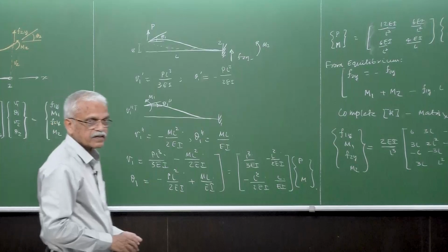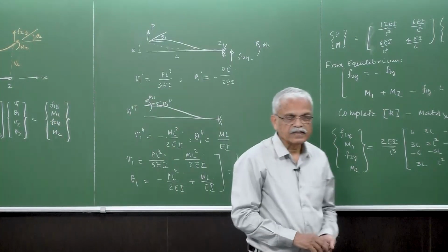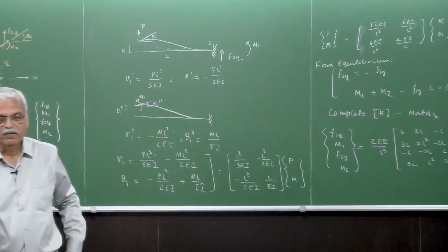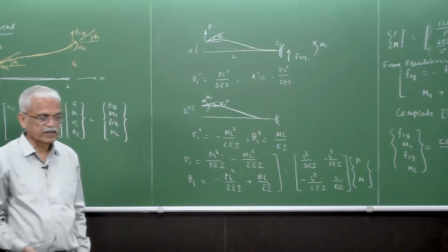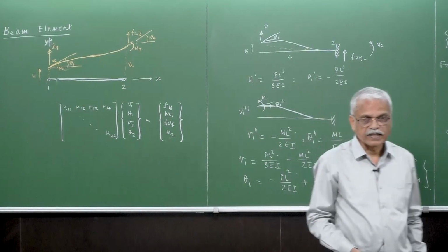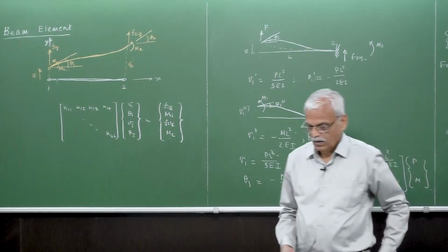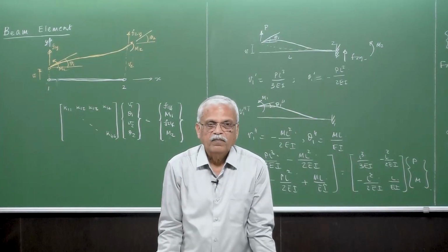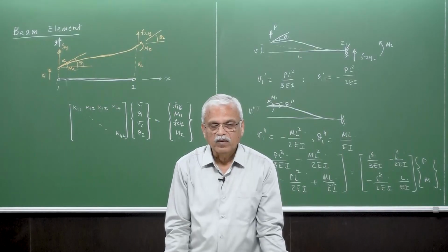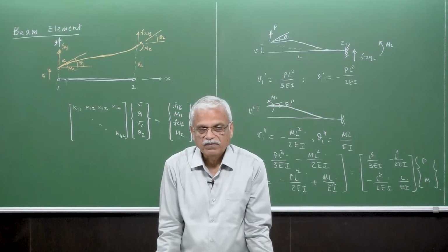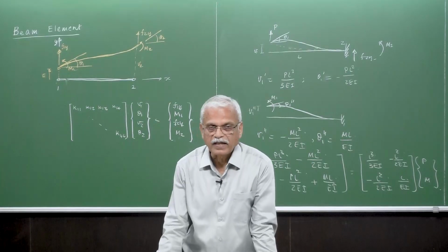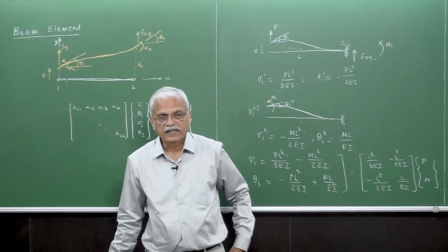So why I took this one is that this together with the truss element will form a frame element. What is a frame element? Frame element is nothing but a generalized one-dimensional element which can take not only the axial loads, but also the lateral loads, including the moments, maybe sometimes even the torsion. So it can even take the bending in other directions as well.